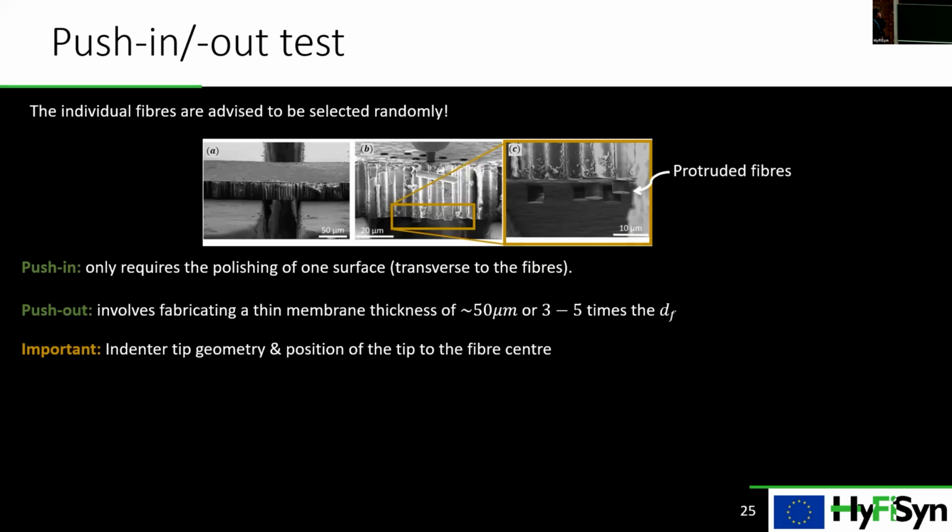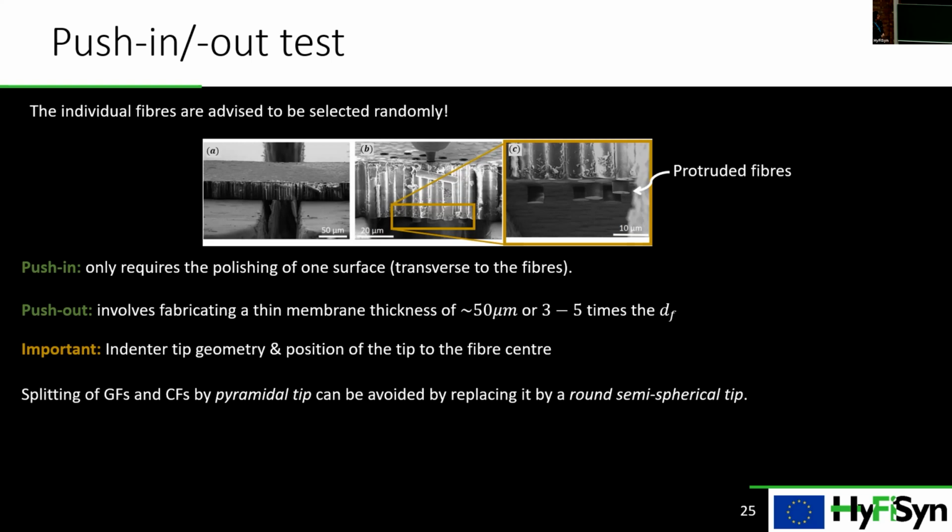And a thing to consider is that the indenter tip geometry plays a big role, and how you also place it on top of the fiber that you are going to push. We can avoid the splitting or rupture of the fibers, for example, by changing the indenter tip to a more proper one. Also, an indenter tip with a larger radius of curvature than the fiber radius is advised against. So it should be comparable to the radius of the fiber.